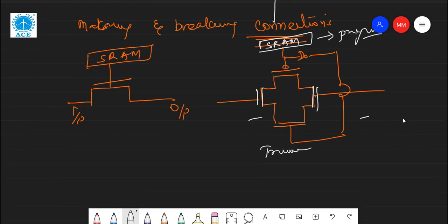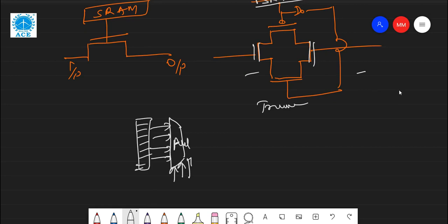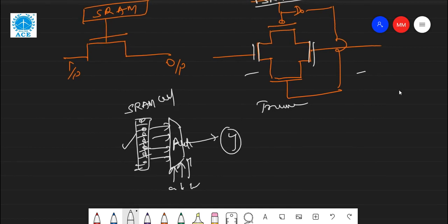Like that, as we know, the MUX, we already discussed the MUX SRAM cell concept. SRAM cells will be programmed here with the connection of MUXes, and these are the select lines we have. Whatever the MUX type, these are the inputs. Whatever the functionality outputs are already stored in the SRAM cell, which are programmed, then depending on that, the selection lines will get the output.